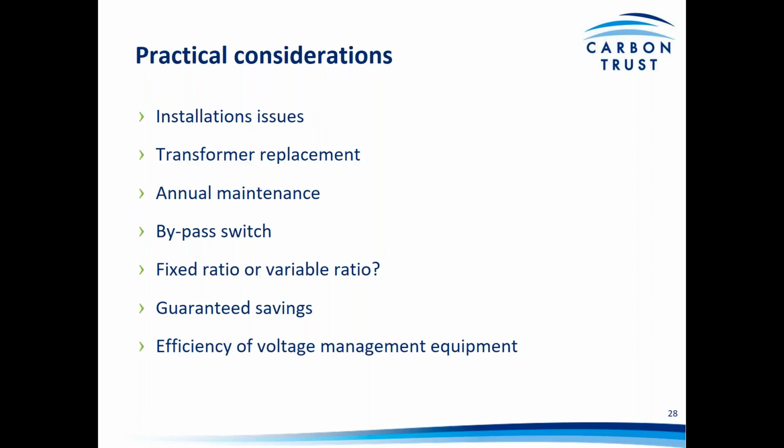Annual maintenance, so does the equipment need to be regularly maintained, and if so, has this been factored into any payback calculations on voltage management? Voltage management equipment doesn't typically need a lot of maintenance, although it is sensible just to regularly check that it is set up to provide the optimum voltage, as the incoming supply voltage may change over time.